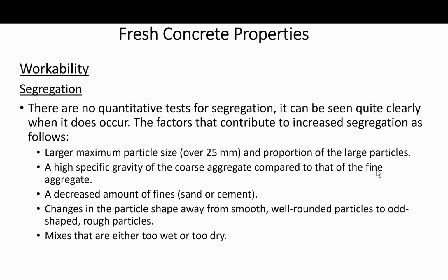Also, a decreased amount of fines, the sand or cement, and changes in the particle shape away from smooth, well-rounded particles to odd-shaped, rough particles. Finally, mixes that are either too wet or too dry also will increase the probability of segregation.